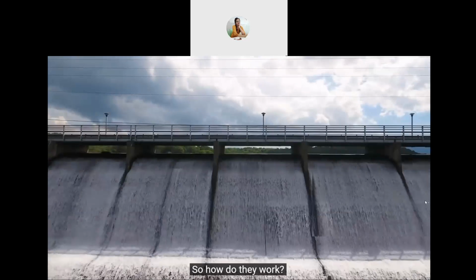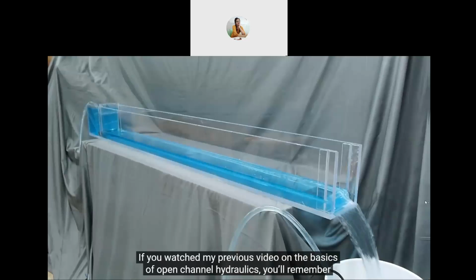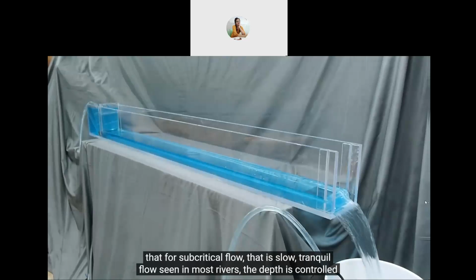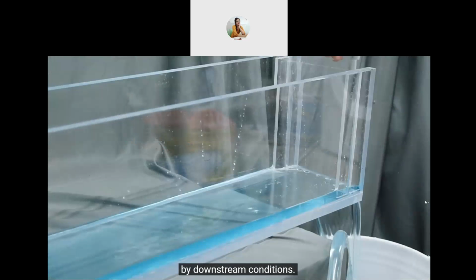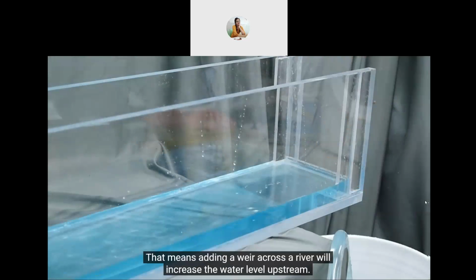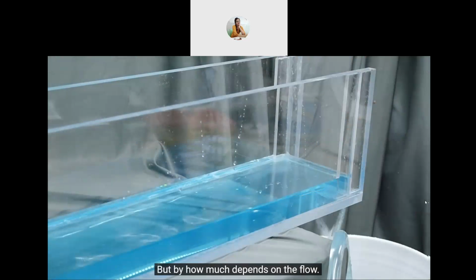So how do they work? If you watch my previous video on the basics of open channel hydraulics, you'll remember that for subcritical flow, that is, slow, tranquil flow seen in most rivers, the depth is controlled by downstream conditions. That means adding a weir across a river will increase the water level upstream. But by how much depends on the flow.